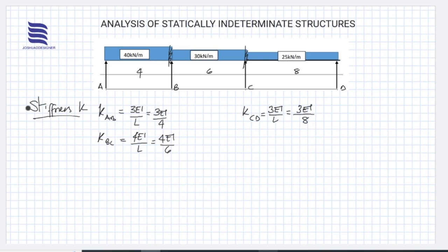So we can have uniformity in our values such that our values will be whole numbers, and we'll take our EI to be constant. So if our EI is constant, we want to see a way where all our results will be whole numbers void of EI. To obtain that, we'll have to find a common factor that can work through all the values we have for our stiffnesses.